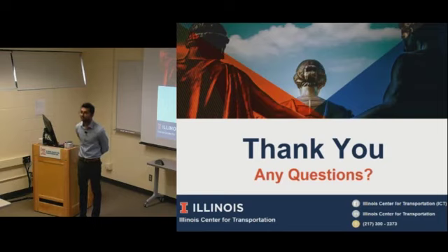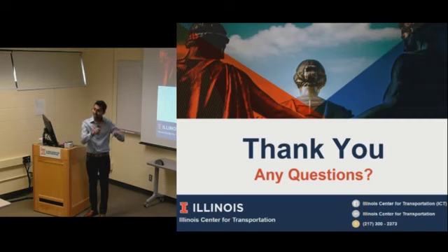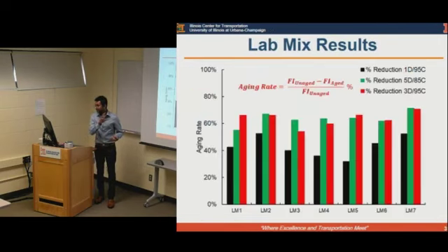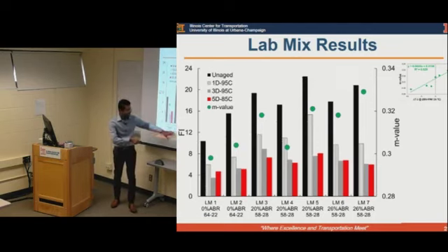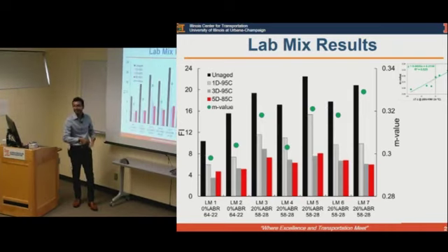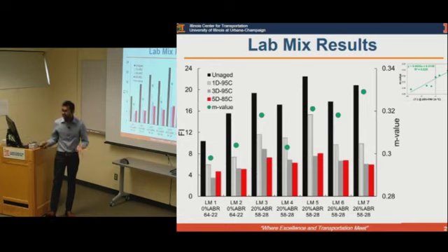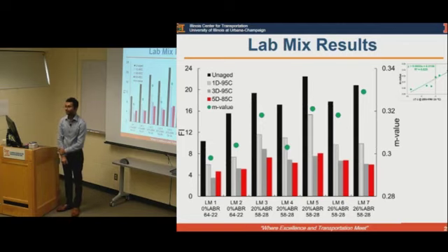So around 25% of RAP was added. Definitely it can introduce that aggregate variability, but from a gradation point of view and volumetrics point of view, those were kept the same. So if we need to compare, that's why we had that subhead, let me go back to the slide, where we were comparing 2 mixes at a time or 3 mixes at a time. If you look here, these mixes have the same RAP, so we can easily compare this, but I cannot compare this to this directly because of the recycled content, and then binder is changing, grade is changing. But yes, that's a valid point that if you have higher ABR, then you will see much more differences coming, not just from the binder source, but also from the RAP. That's true. Yeah. Thank you.